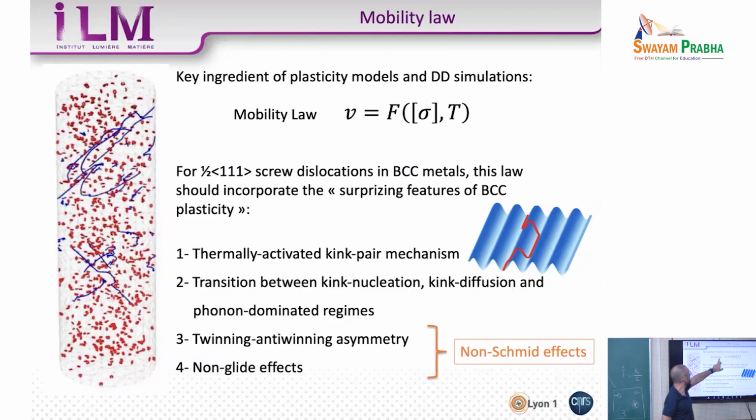And this mobility law is at the basis of all the dislocation dynamics simulations, because you use the dislocation dynamics to tell you what is the local stress tensor, you know the temperature, you get the velocity, and then you move the segments according to that velocity, and you recompute the stresses, and you do it all over again.